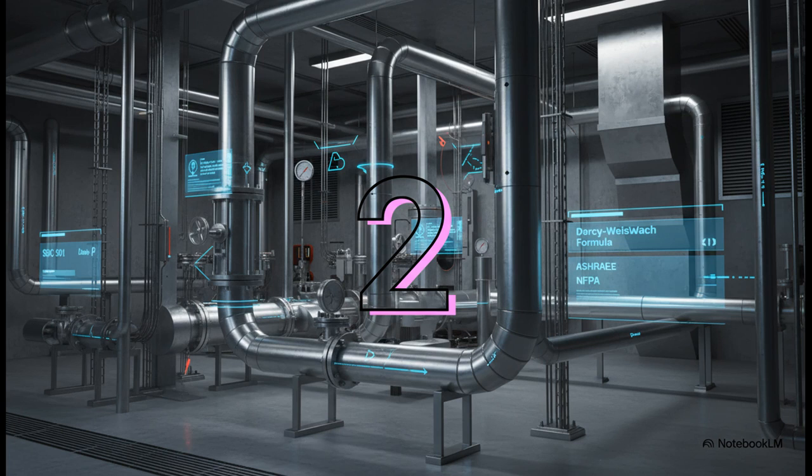Now for the really crucial engineering check. When you add length and bends to a pipe, you increase friction, which changes the pressure drop in the system. You have to recalculate it. This formula here is a simplified version, but it shows the principle. This step is what proves that your system will still work as designed and that it still complies with codes like SBC 501. You have to prove that your fix didn't just create a brand new problem downstream.